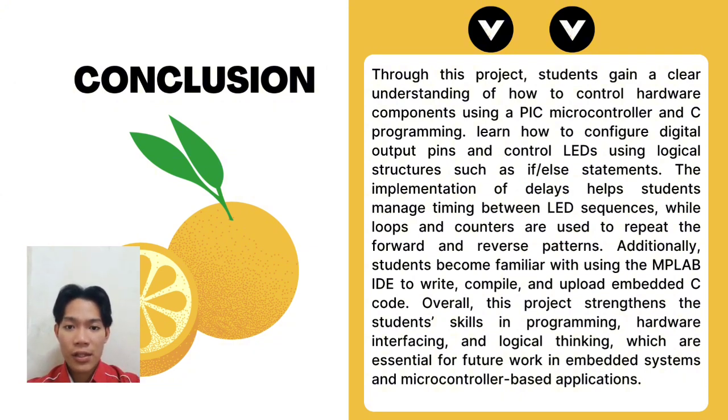The implementation of delays helps students manage timing between LED sequences, while loops and counters are used to repeat the forward and reverse pattern. Additionally, the students become familiar with using the MPLAB IDE to write, compile, and upload embedded C code.